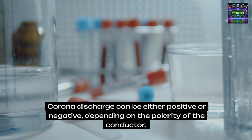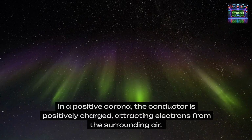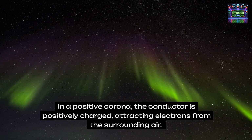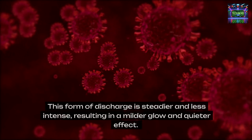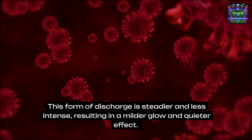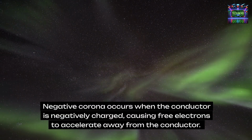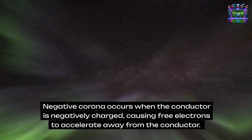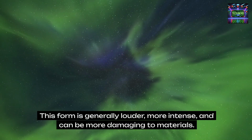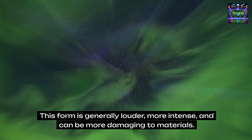Corona discharge can be either positive or negative, depending on the polarity of the conductor. In a positive corona, the conductor is positively charged, attracting electrons from the surrounding air. This form of discharge is steadier and less intense, resulting in a milder glow and quieter effect. Negative corona occurs when the conductor is negatively charged, causing free electrons to accelerate away from the conductor. This form is generally louder, more intense, and can be more damaging to materials.